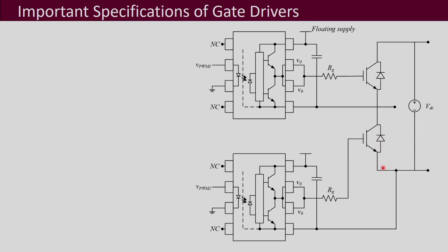For that, I have taken this example of one leg of an H-bridge, and this is your optocoupler based gate driver, where you have this optocoupler, and then this totem pole arrangement is also there. Now, what you have over here on this side is the PWM inputs that are going to be coming, PWM 1 and PWM 2 for these two IGBTs, and then the output is going to appear on this VO point. Now, two of them have the same VO.